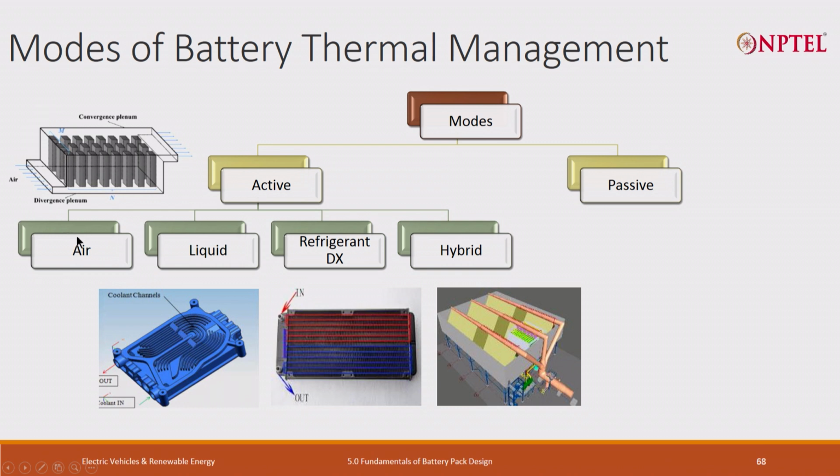So, you should have sufficient energy available in the battery pack. That means the battery pack should be sufficiently large to utilize an active cooling system. When your battery pack is small, what should you do? In such cases, the passive cooling system, which does not draw any energy from the battery pack, is mostly used.